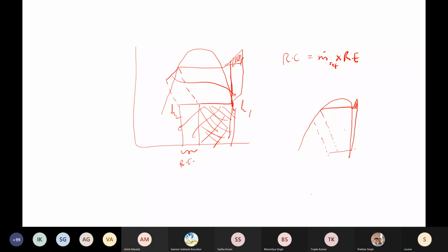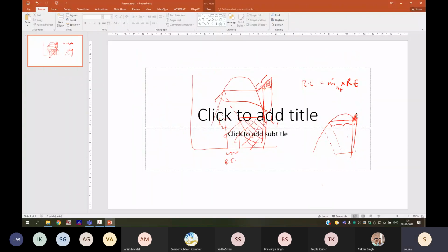Is this true or false? You can check this from the graph itself. The majority of the heat transfer for a refrigerant with a smaller superheat horn happens in the two-phase region, with a very small amount in the sensible region. Whereas a refrigerant which has a very large superheat horn will have a large fraction of the heat transfer happening in the sensible heat transfer region. In the extreme case we discussed, the type 3 refrigerant, there was no superheat horn. After compression, we entered the two-phase region, so there won't be any sensible heat transfer in such a refrigerant.